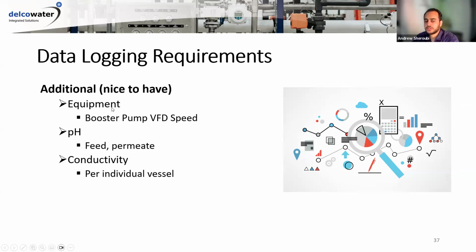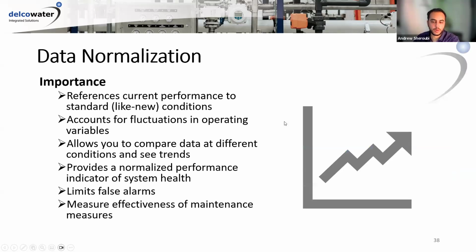Additional nice to have, if you have a booster pump and a VFD, it's good to know the speed. And it's also good to get the pH and conductivity per individual vessel. This might be a bit overkill per vessel, but per stage is probably okay.